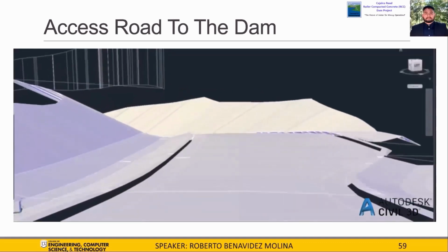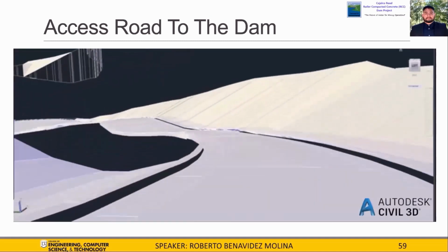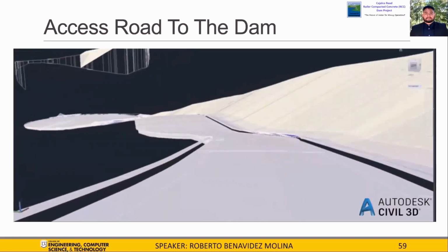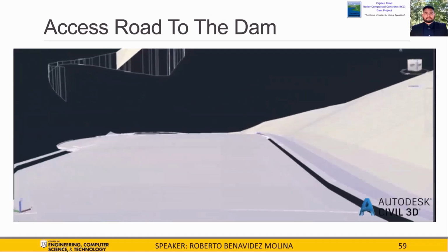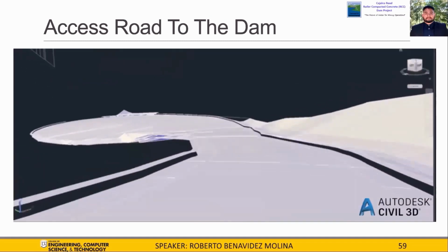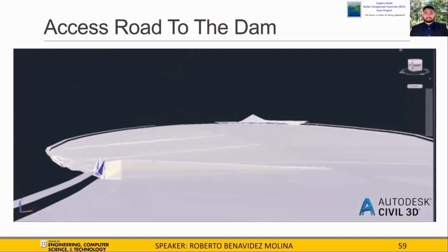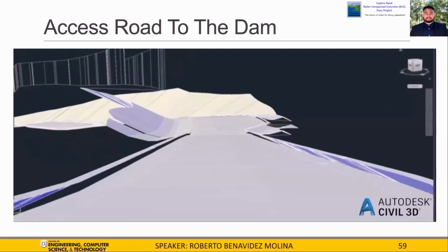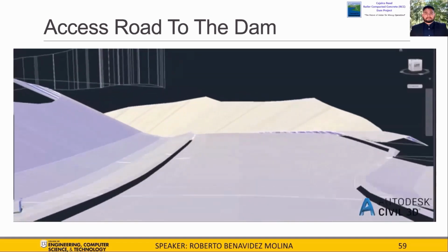During the design process, our goal was to design a road considering cost efficiency, earthwork, and materials required. These factors led our team to implement a retaining wall with a max vertical height of 30 feet that will span 410 feet left of the road, reducing the overall amount of earthwork needed. Implementing a stable retaining wall will prevent any possible soil failures as well as maintain the height of the soil.